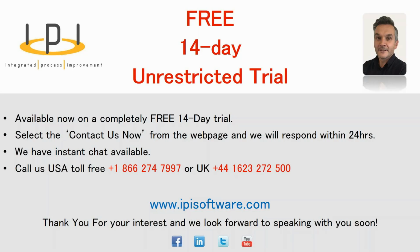So we've got a question here. Is there a minimum number of measurements required before CPK values are calculated? Well, the answer to that question is really guided by the customer. Typically when you're doing SPC, they may require 25 results, 30 results, 35 results. The fact is, it is down to the calculation. So any forms we show, any calculations we show, are based on the number of results that you've got at that particular time. But to give confidence, you'll be guided by the number of results that you may have to use.